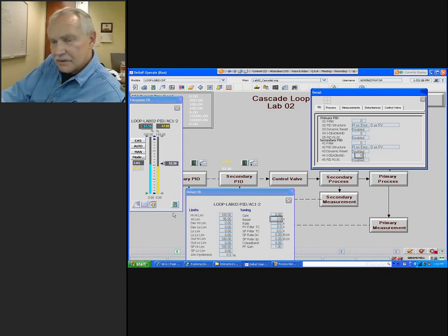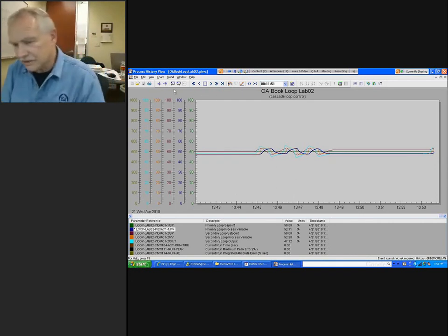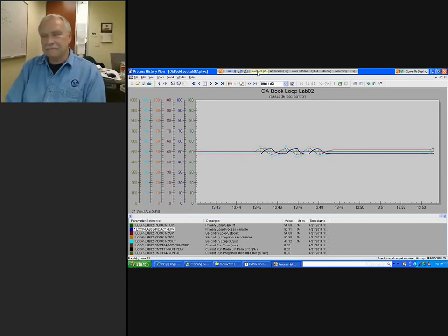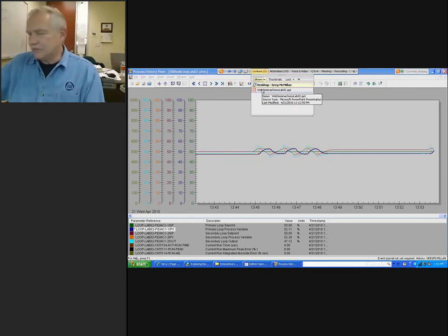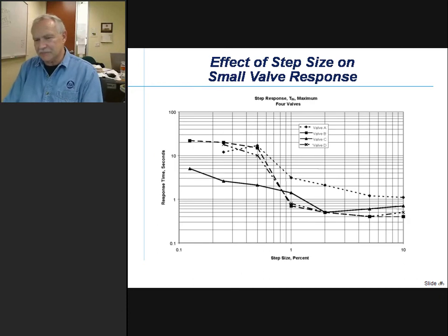Talk a little bit more about how you really test a control valve. And one of the things that is a common problem, and that dates back to the 80s and 90s, is that we tested control valves by introducing, say, a 50% signal, and somebody would go out to the field, and we didn't have position feedback, so we thought, oh yeah, it looks like it's about half open. Then we put the signal at 100% and said, oh yeah, it looks like the valve's fully open, and then we thought we had checked out the valve.